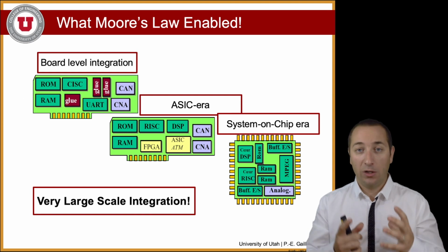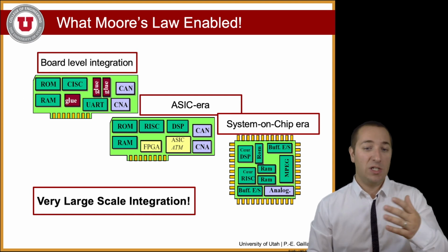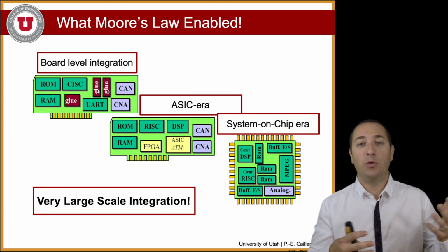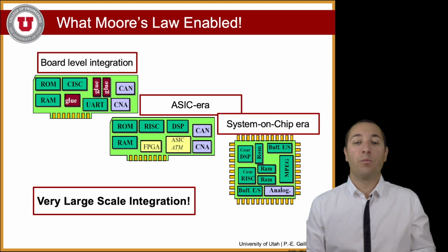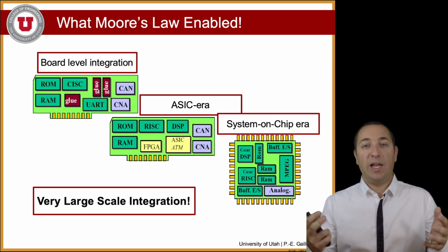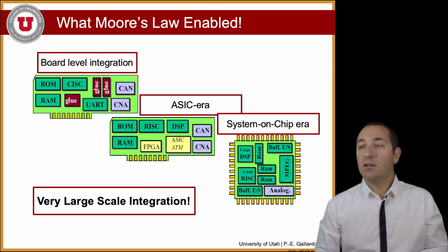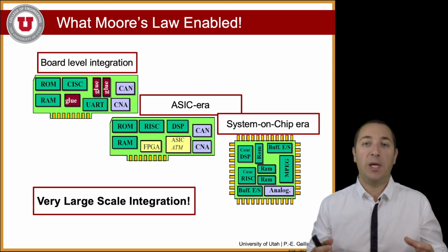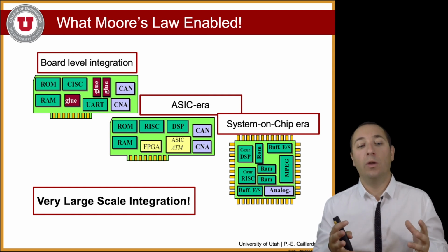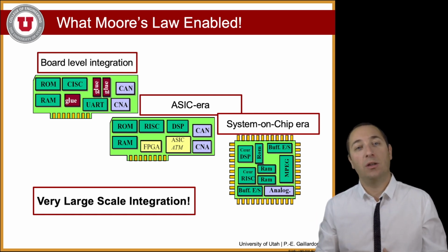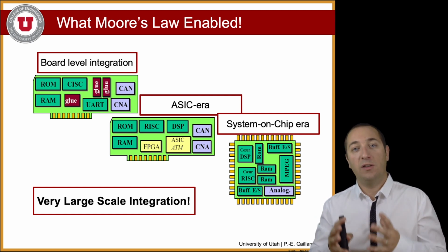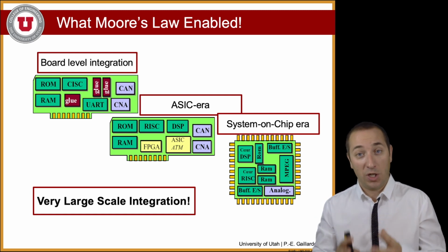You will find a single chip that will contain a DSP core, a processor core, various input and output systems, complete video encoders and decoders, for example. Plenty of microcontrollers are like that. Fancy microprocessors and FPGAs are doing exactly that. And that's what is called very large-scale integration. Very large-scale integration of transistors to enable the very large-scale integration of functions on the same chip.